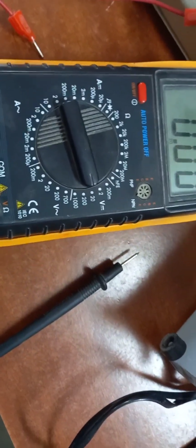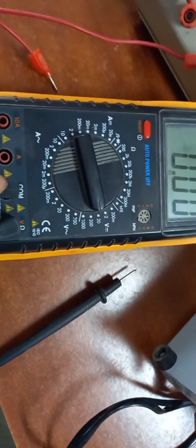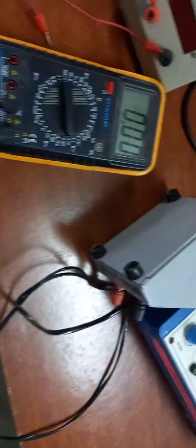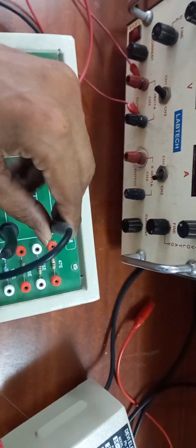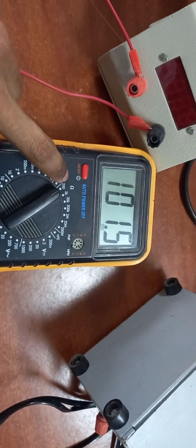Then I am going to take one multimeter here. You remember, this is a multimeter. It can be used for both voltage and resistance measurement. I have taken this pin and connected the common terminal. Then I am going to connect it where we have made the open circuit in the Thevenin circuit. That place only we can put the multimeter. We keep the multimeter in ohms, since ohms find the resistance.